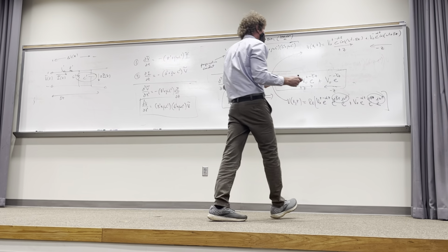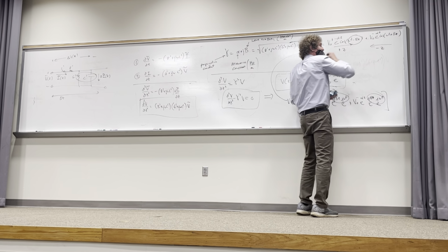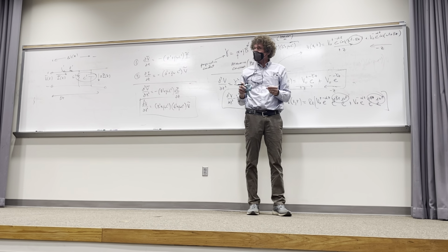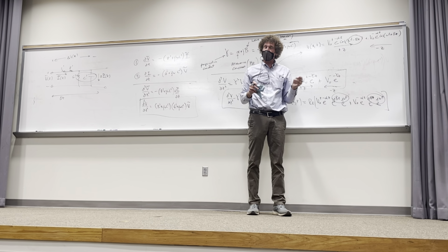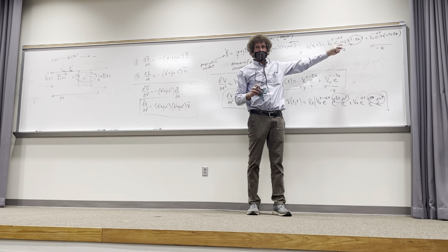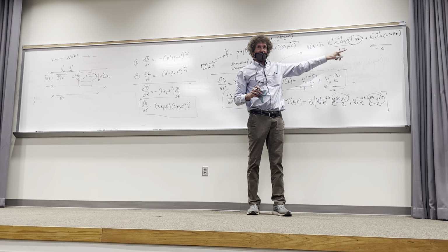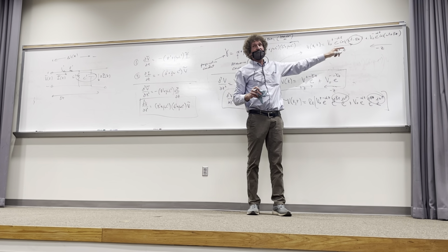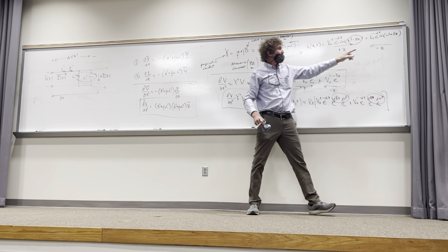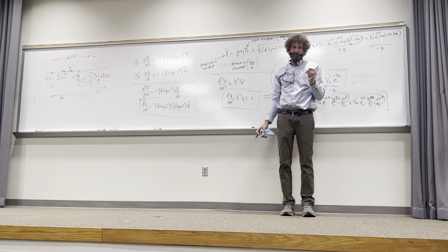What did I do to get phase velocity? Well, the hint is phase. Do you all agree that's the phase right there? Velocity is always something to do with the rate of change with time. So if you take a derivative of that with respect to time, you get omega minus beta dz/dt equals 0. Correct, class? Then you take omega to the other side, and you get dz/dt equal to omega over beta. That's positive. It's moving in the positive direction. If you do the same thing over here, that's moving in the minus z direction. It's the phase.